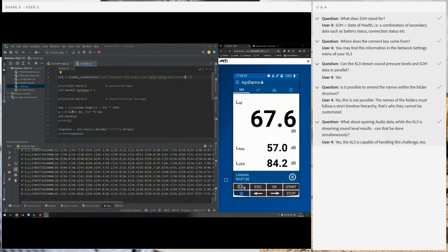Yeah, and we are sending here audio, and we tell again the device from which epoch time we want to have the audio. This could be back for a few days or just a few minutes or whatever. In my case, I'm asking the device, give me the audio which we have recorded 60 seconds ago, and then 3 seconds portion of it. You could choose here 10 minutes, an hour, it's on you. Just the amount of data will be pretty huge.